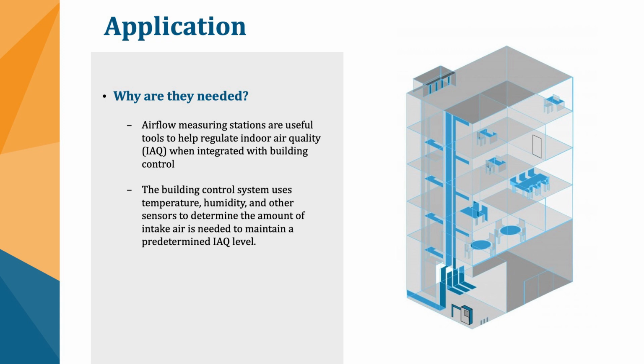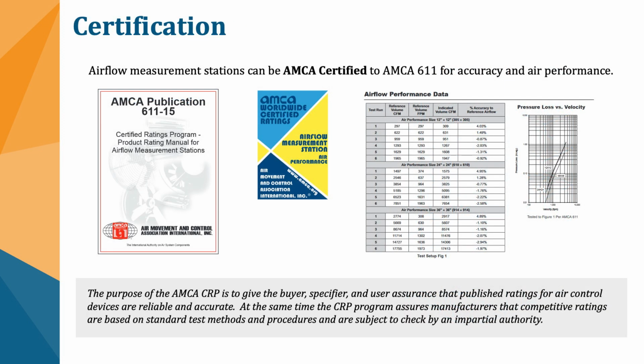And they're going to take a signal from those airflow measurement systems and go back to a pre-programmed set of controls, or something that may respond to certain pressures, whether there's certain limits for temperature or potentially CO2 sensors, or just overall flow that's calculated in. It can work all those ways. And at that predetermined level, it can either take in more intake air that will have to then be conditioned, or recirculate the building air.